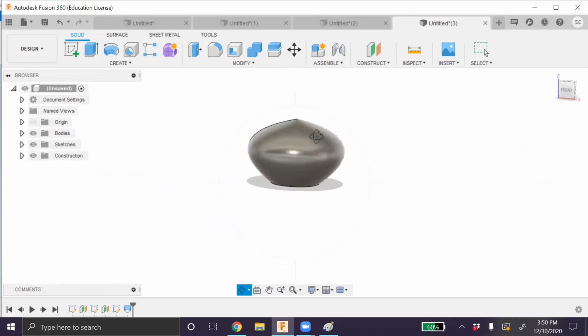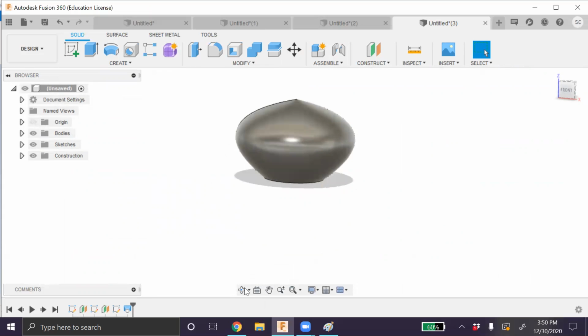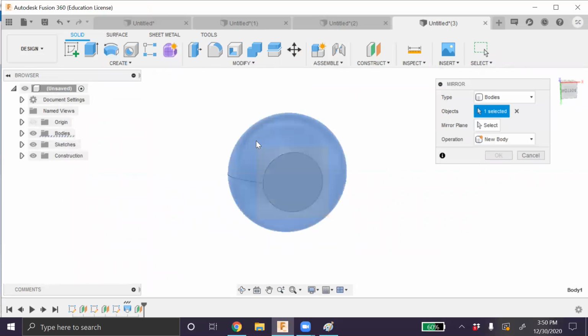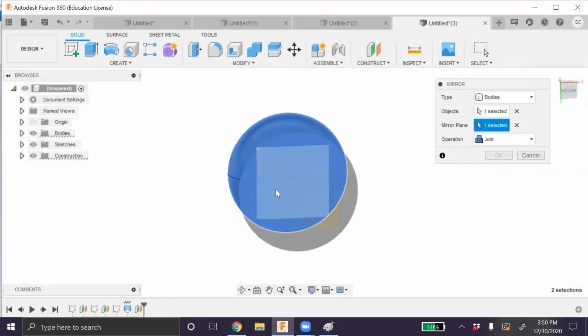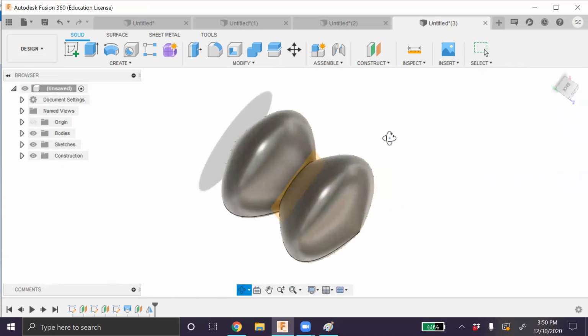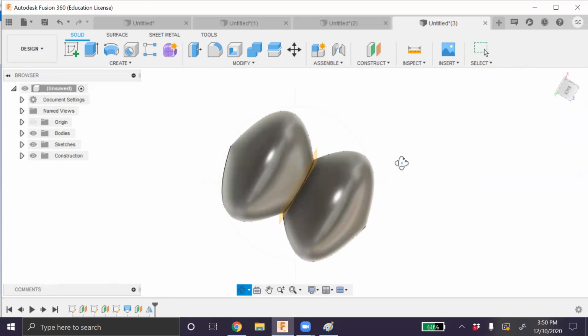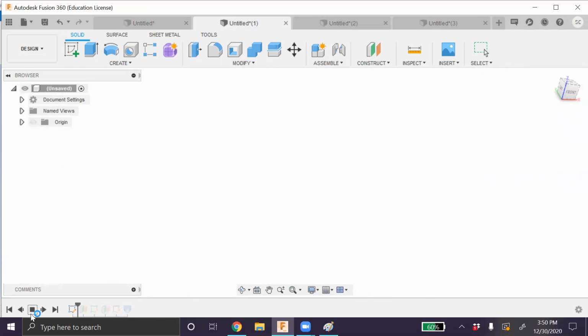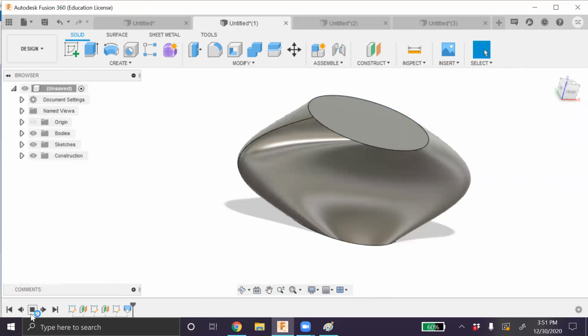So what I have over here is a kind of surface with a general increase in its slope and then a drop, more like the second half of a top. If I want to make a top out of this, I'm just going to construct an offset plane, and I'm going to go ahead and mirror, taking this plane. So this is what a Loft command can do. It can create different kinds of bodies. For example, in this one, I drew a circle, then an ellipse, and then another circle, and then I used the Loft command. So I got a shape like a paperweight of this size.